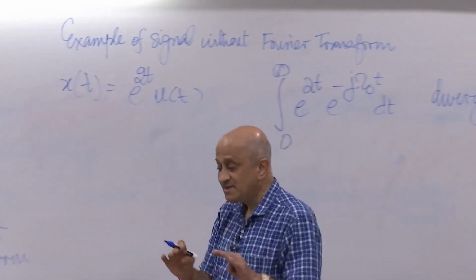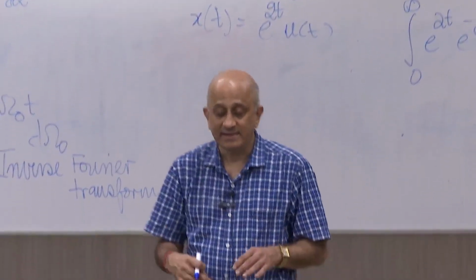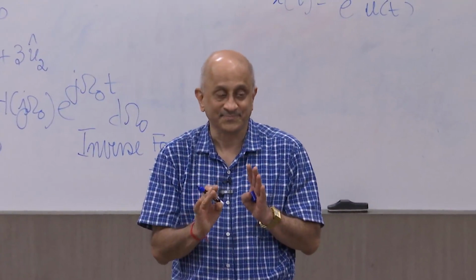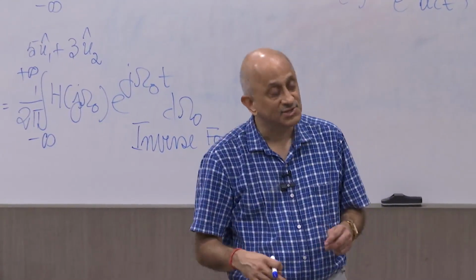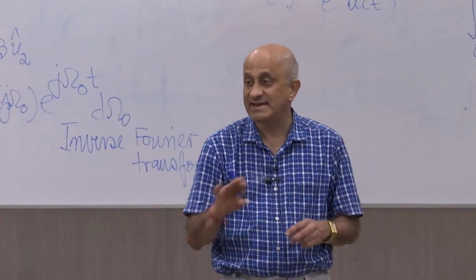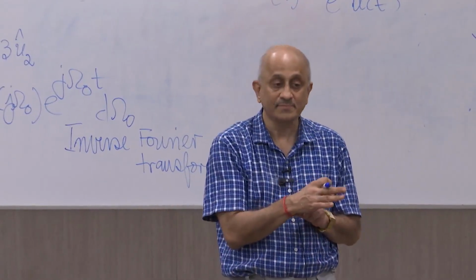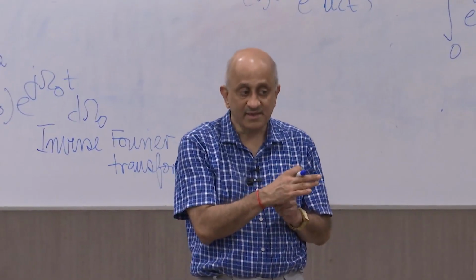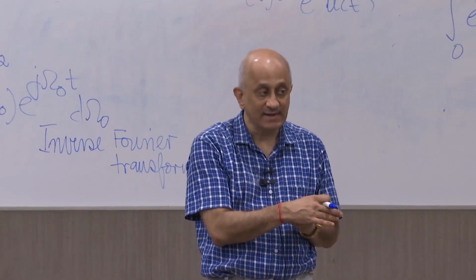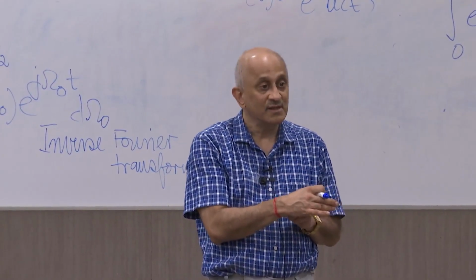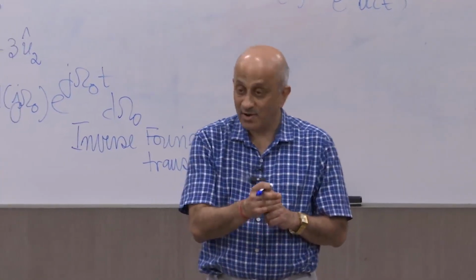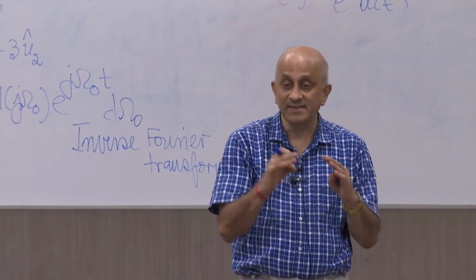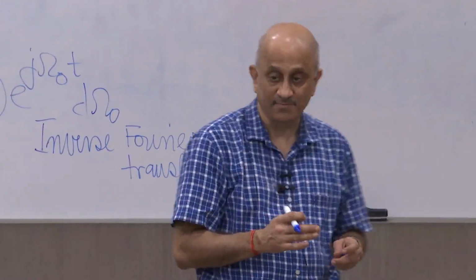So that's why I'm just trying to emphasize why we need to say that you're confining yourself. You're not looking at all possible signals. The convolution relationship is most general for a linear shift invariant system. But what we are doing now in the Fourier domain restricts itself to those signals, those systems, or those situations where all the signals involved have a Fourier transform, right?